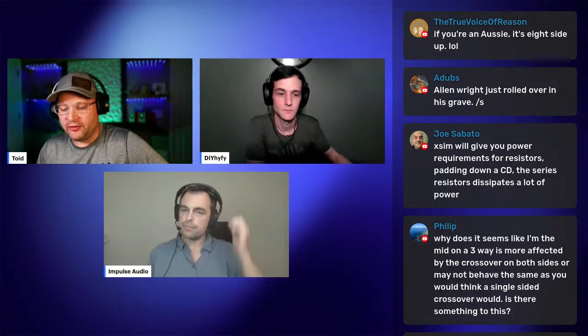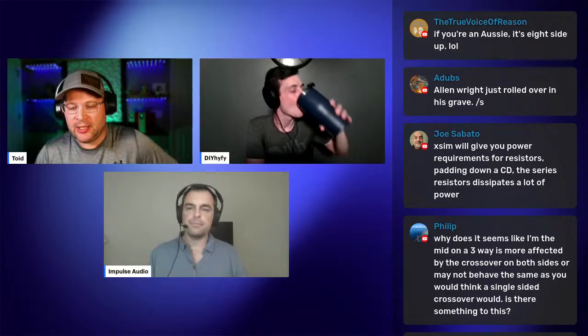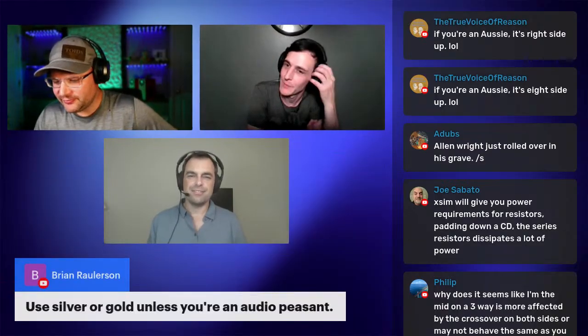The biggest reason why is your drivers are going to have different sensitivity, meaning the amount of wattage going to each driver is going to play at a different level, and your tweeter is almost always going to play at a higher level than your woofer. There are some cases where that's not the case, and you just need to scrap that design. That's an issue for driver selection, which I think we did a few episodes back.